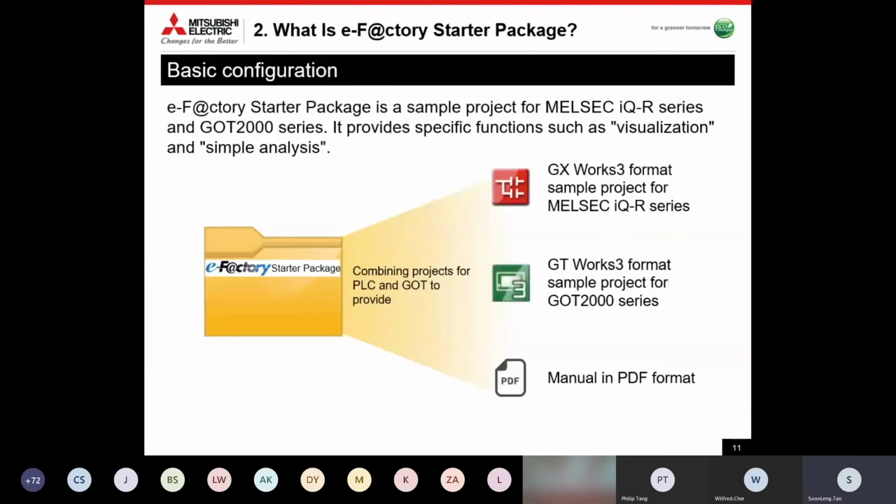So what is the basic configuration in this starter package? Today I'm talking about the sample project that is available for our iQ-R series PLC and GOT 2000 series HMI. In this package, you will see three components providing you visualization and simple analysis functions: a GX Works3 format sample project for your iQ-R PLC, a GT Works format sample project for your GOT 2000, and a manual. This manual teaches you how to set up the functions to do your OEE functions.